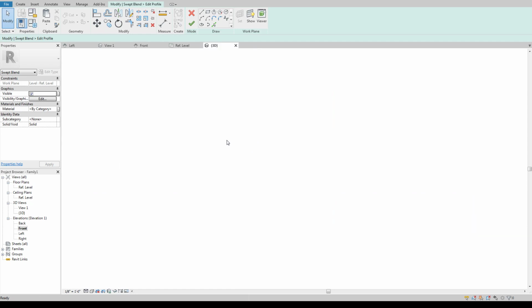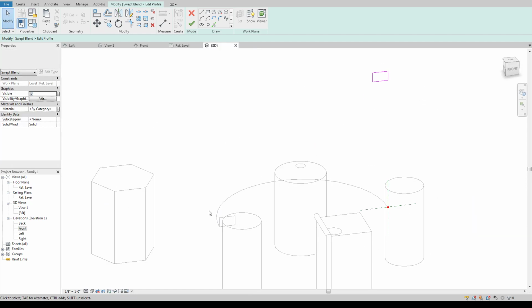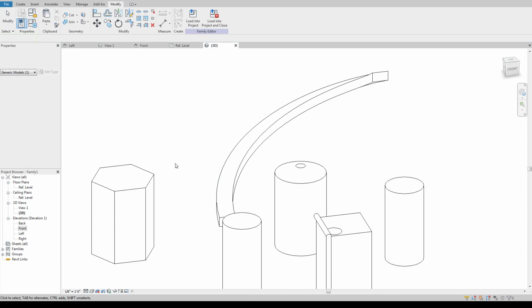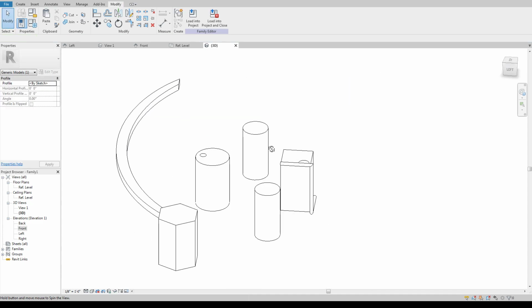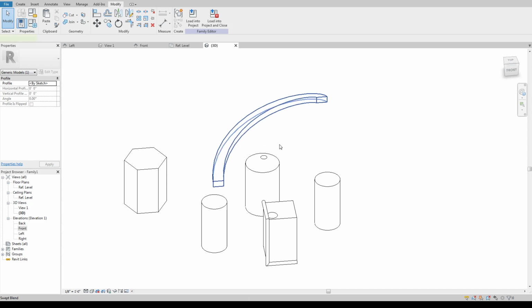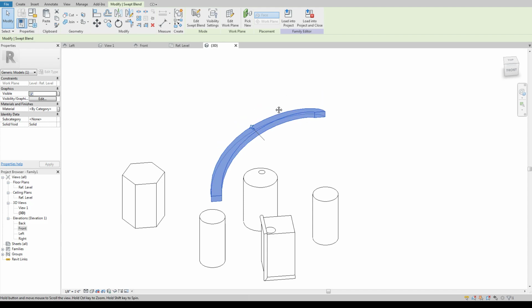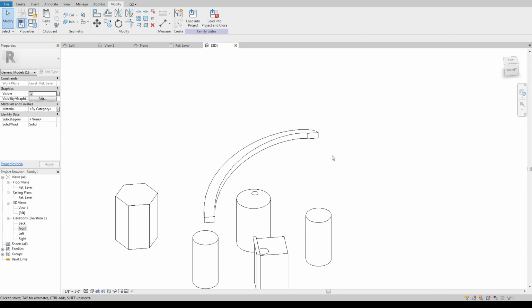That's where this tool can be helpful, because you can draw the exact same profile and then say, okay, I'm bending around the outside. I know how far up I need it to go based on how many risers and stairs I've got. I hit my green check mark and it'll go ahead and bend that up and around. So you can create those kind of shapes like a helix. You could create this kind of helix by just copying this shape up and then mirroring it across, and then you get that helix shape over and over again all the way up.